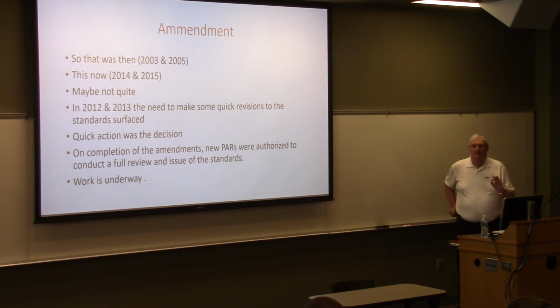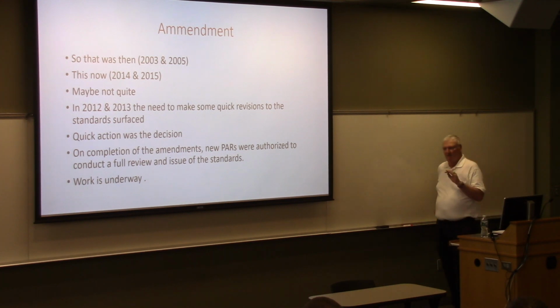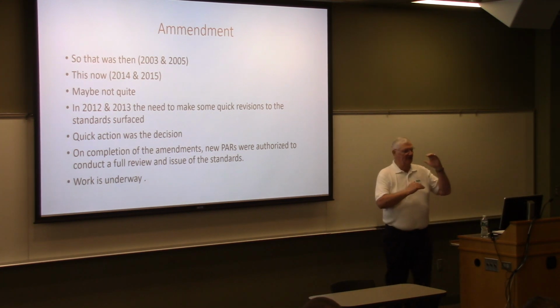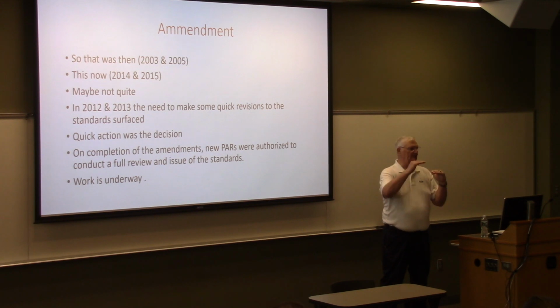But the problem is that a solar photovoltaic system and a wind system make their return on kilowatts. Not on kVA, but on kilowatts. So if I have a 10 kW solar farm, that's 10 kVA. And if I say all of a sudden, instead of giving me 10 kilowatts, give me 6 kilowatts and give me 8 kVAR. Well, I'm only paying for the 6 kilowatts. I'm not paying for the 8 kVAR. So the problem is the return on investment goes down the tubes.